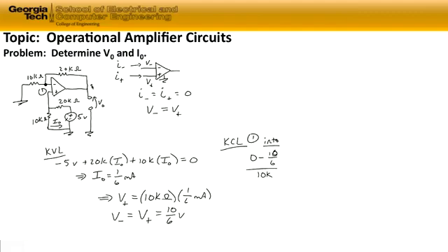It's going to be Vout minus 10/6 volts divided by 20K. So that's the current flowing right to left into node 1 through the 20 kilo ohm resistor. We also have the current flowing out of the inverting input of the op-amp, which we know is equal to 0.